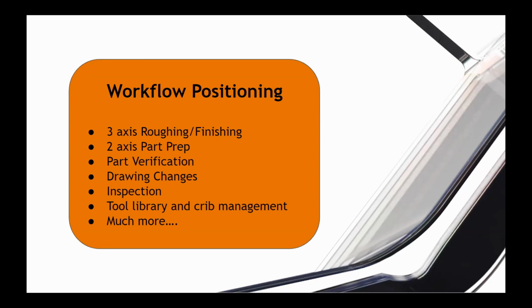And when it gets to my more bottleneck machine, meaning a full 5-axis machine like a UMC or DMG or something like that, you don't really want to tie up those bottleneck machines just for roughing and for doing simpler things. You want to make sure that you're maximizing the efficiency of the machines that you can use for their full 5-axis simultaneous toolpaths, right?